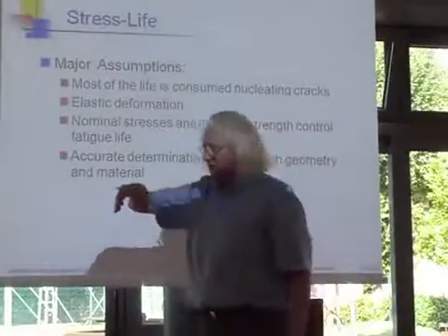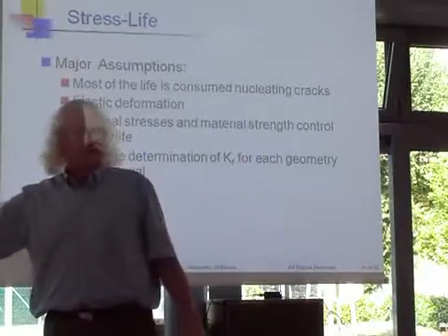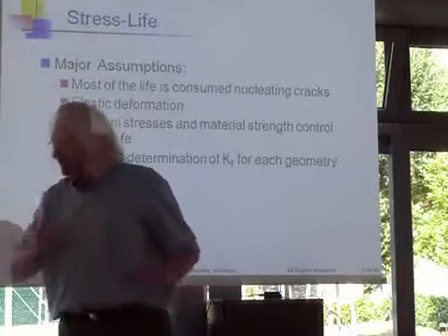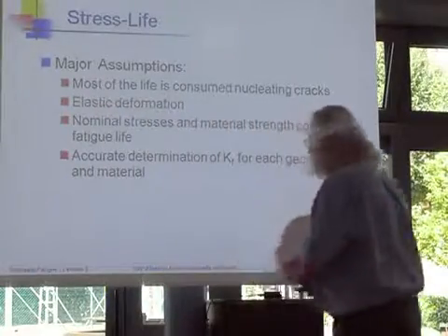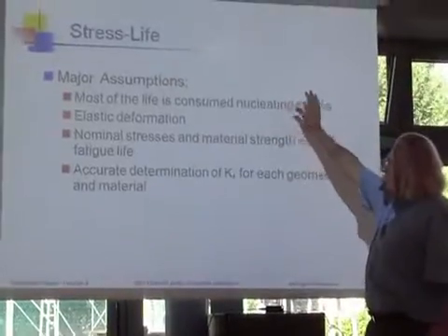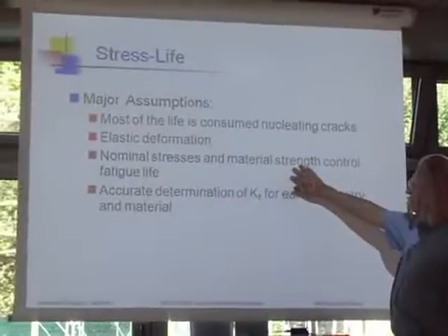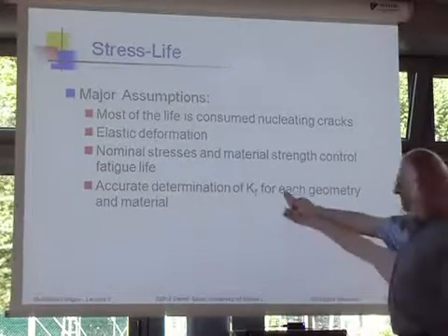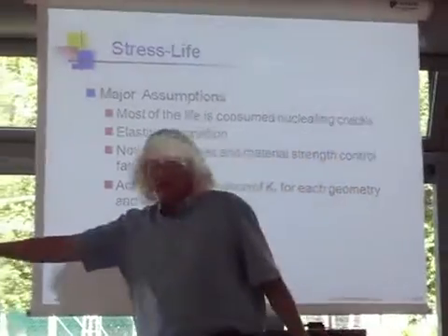Bolts essentially develop cracks on the preload cycle. Every bolt in there has got a little crack in it, and they grow very slowly to fit. So those are the assumptions that maybe we don't think about, but that's the assumptions we make. That means a nominal stress and material strength control fatigue life. And to make all this work, you have to really understand these little stress concentrators.